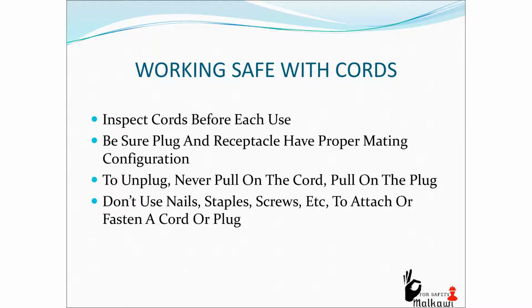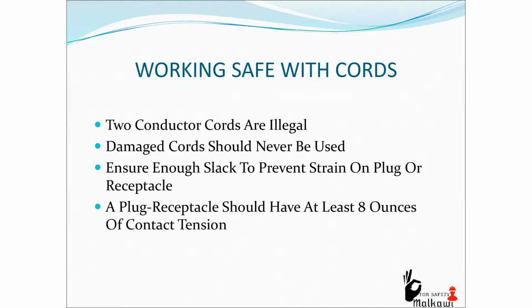Working safe with cords. Inspect cords before each use. Be sure plug and receptacle have proper mating configuration. To unplug, never pull on the cord; pull on the plug. Don't use nails, staples, or screws to attach or fasten a cord or plug. Two-conductor cords are illegal. Damaged cords should never be used.